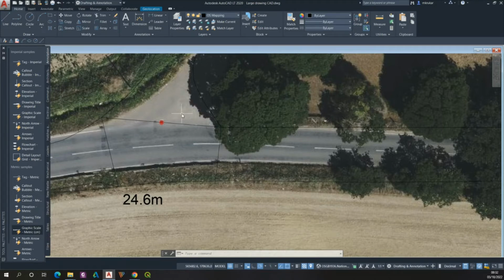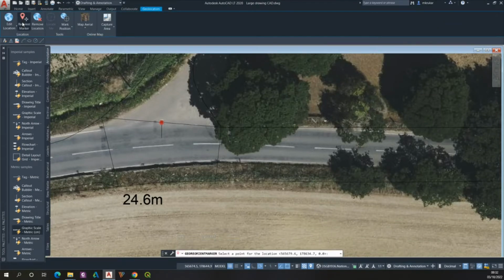I have forgotten recently. I cannot draw the line towards this direction because the system is upside down. So I need to pull the line towards this direction, towards down. So by starting from this point, I need to pull down 2.3 meters, right? And then my line will be like here, and now I can go back to the geolocation and reorient marker. My new place will be the endpoint of the new line drawn, which will fall here.